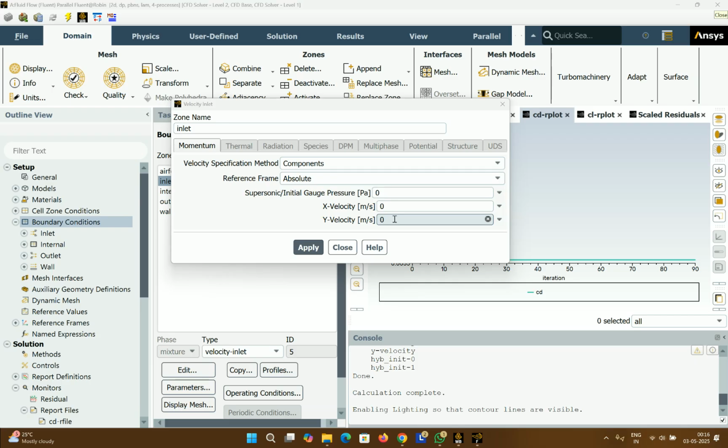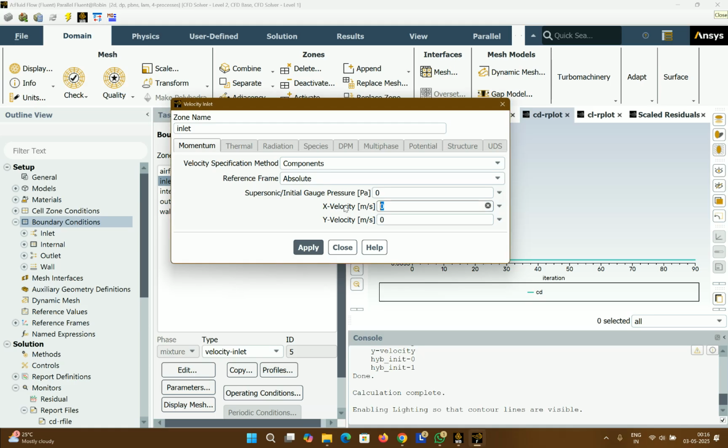So if you want to organize that in terms of x and y velocity, because that is a component of velocity which is at an angle of 5 degrees with your aerofoil. If you want to change the angle of attack to 5 degrees, the easiest way to do that is using the values here. Again, these are just trigonometric relations that we're developing. In x velocity, you will have the value as velocity times cosine of your angle.